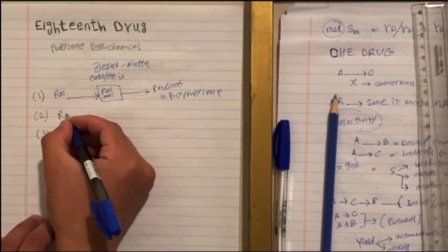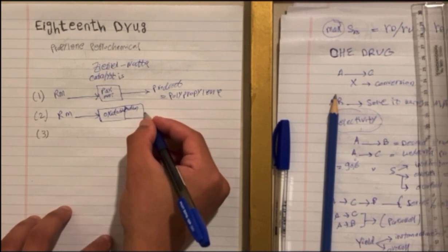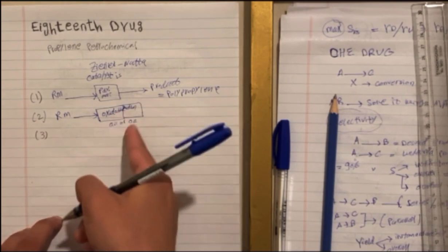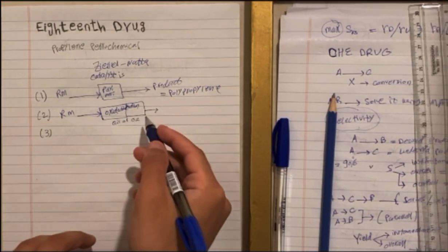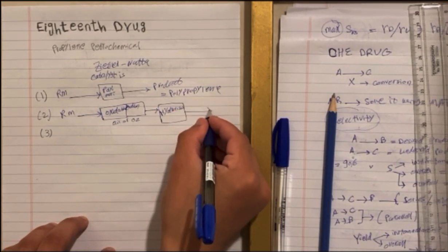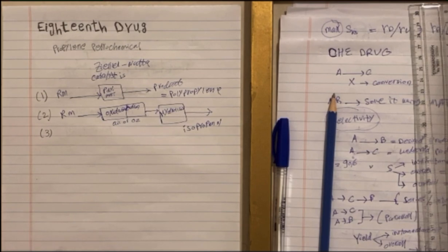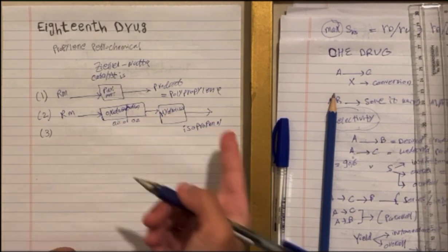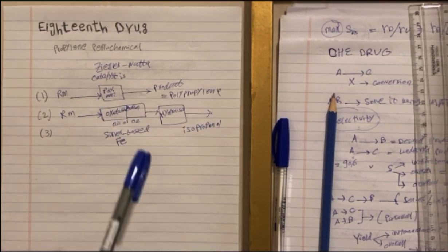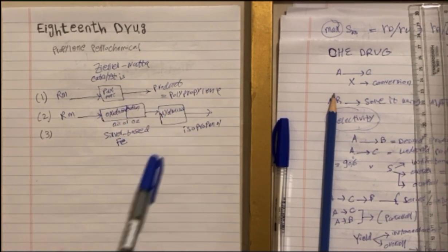It can also be used as a raw material to make, through oxidization, propylene oxide. And this can be done if you enter air or oxygen inside the oxidization process. Then the produced propylene oxide will enter a hydrolysis process to add water, and then it will form what we call isopropanol, which is the one that we discussed before, used for hand sanitizer sometimes. The catalyst used in this process is sulfur-based. It has to contain Fe that converts the propylene into propylene oxide, and then adding water will produce isopropanol.